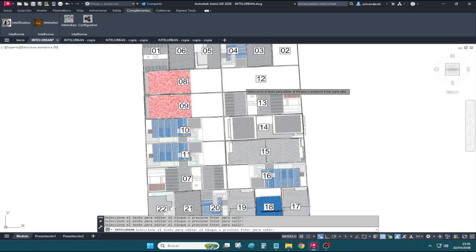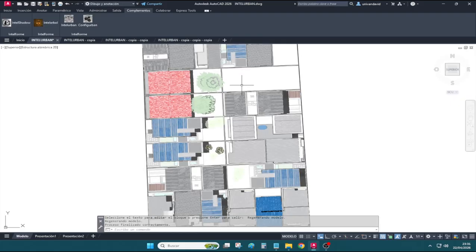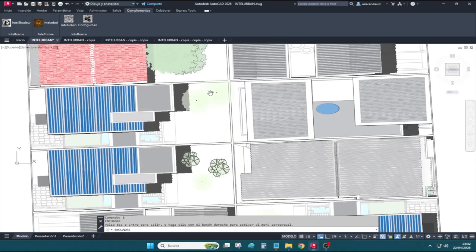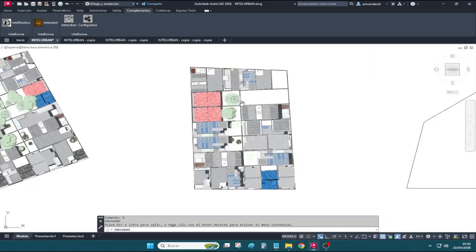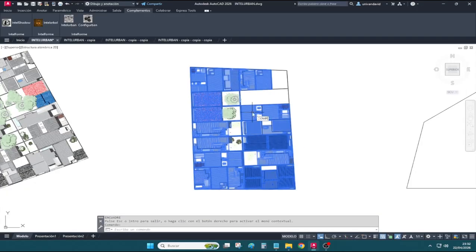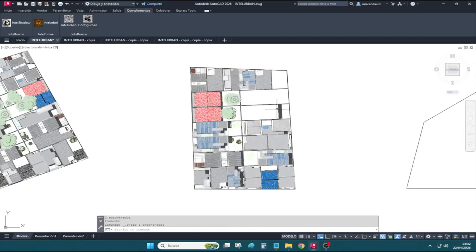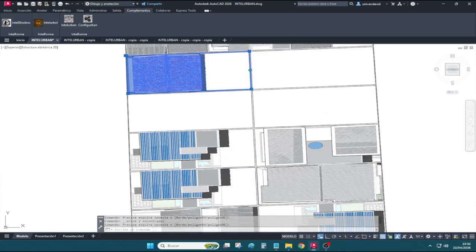Press Enter to finish generating drawing details, shadows, trees, textures, and other graphics. The final output is one block you can explode and edit freely, since all generated parts are native AutoCAD entities.